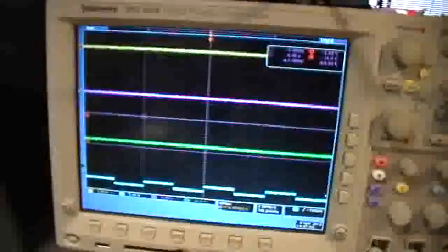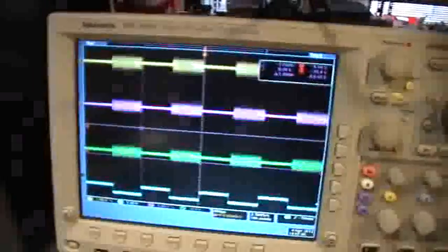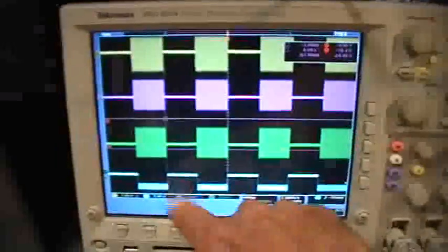Okay, so there's that. So if I vary the function generator amplitude, you get the characteristic things, right, where the oscillations are dependent on the function generator drive. And notice where the trace is on the current viewing resistor. It's right at 0. It doesn't deviate from 0 here because I've got a negative drive pulse.